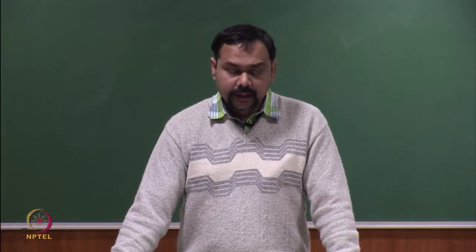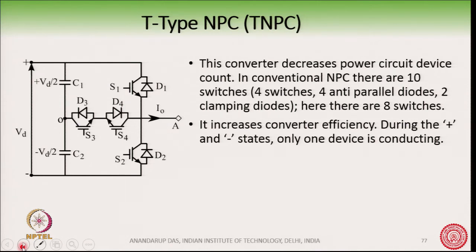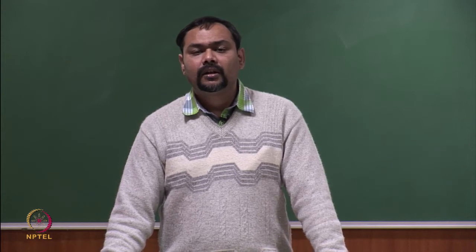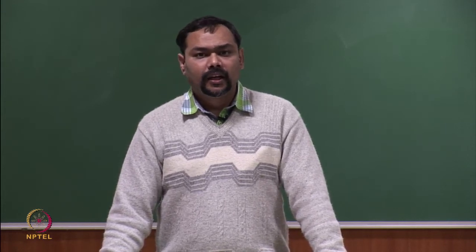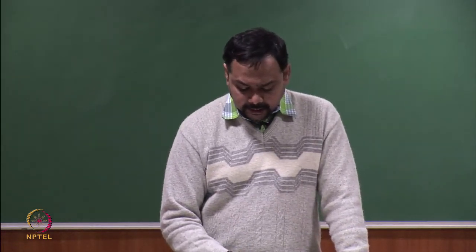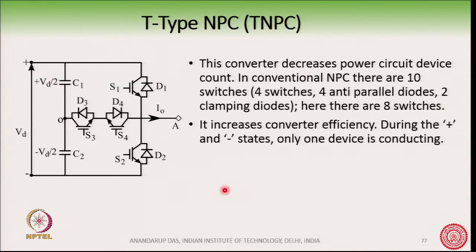Of course, these 8 switches have different voltage ratings, but overall it has been reported that this increases the converter efficiency. You can easily understand that when you have the plus and the minus states, only one device is conducting in this topology, whereas in a 3 level NPC during the plus and minus states 2 switches are conducting. So, it has been reported that TNPC actually increases the converter efficiency.